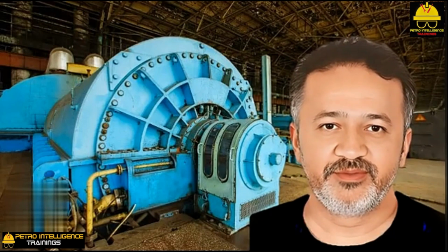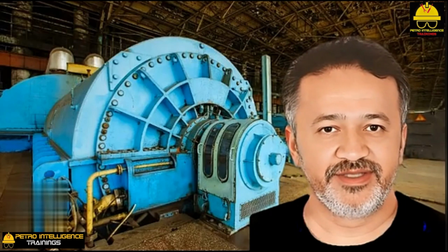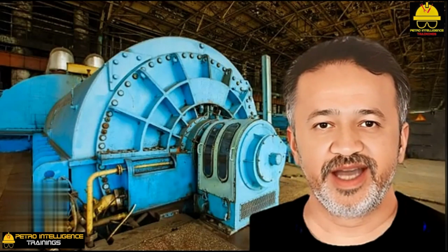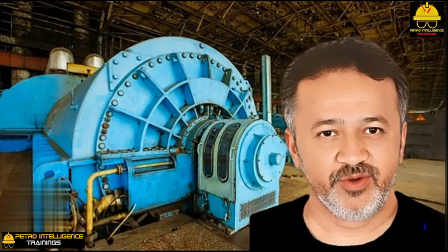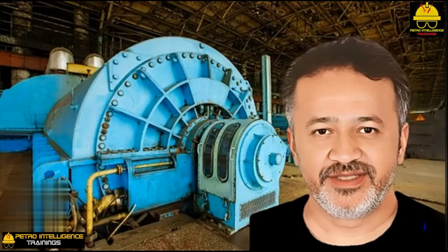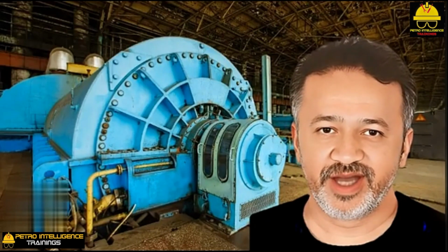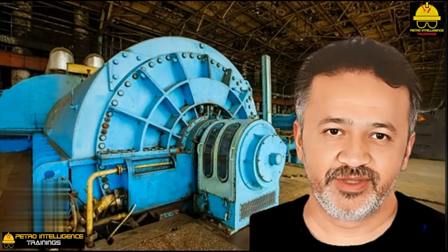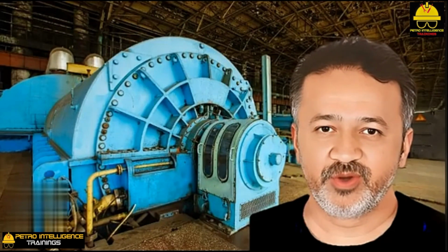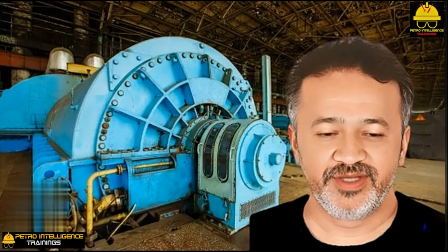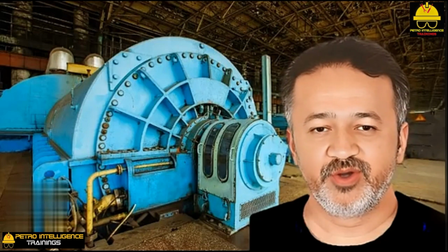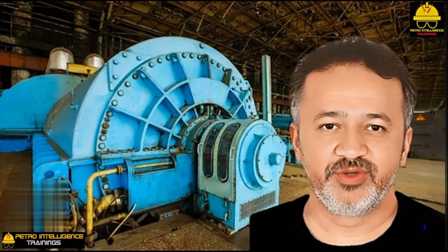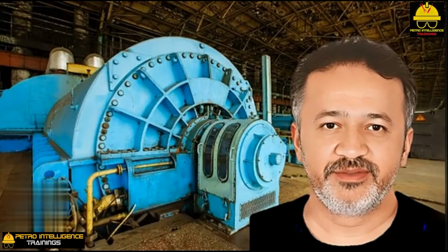There are 2 general types of steam turbines, extraction and condensing. The most common turbine with which the process operator comes into contact is used to spare an electric motor-driven centrifugal pump. The 3-phase AC motors used in the United States and South America are either 1800 or 3600 RPM. The motors used in Europe are 1500 or 3000 RPM. Small steam turbines, 20 to 500 horsepower, used to drive centrifugal pumps are rated for the same speed as the electric motors that are used in that particular service.